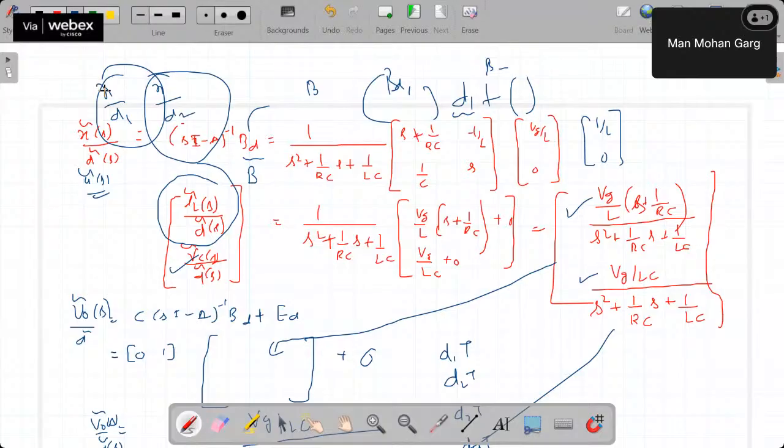Now in a multi-port converter, we do the same. But sometimes issues like cross coupling and cross regulation occur in multi-port converters. Then we use decoupling and such, which are different control approaches, right? But yes, variation of duty cycle D1 may affect both output voltages if there are multiple outputs. So we need to know that this way only.